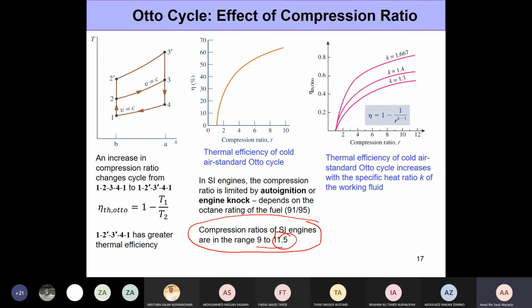We can replace the fuel by methanol, and we can do that. We increase the efficiency if you use methanol as a fuel? Yes. How do you increase the efficiency? Because you're saying the compression ratio can go high? Yes, that's right. So methanol has an advantage that it's not very reactive. So yes, you can go to higher compression ratios.